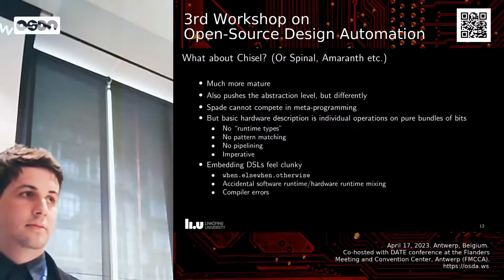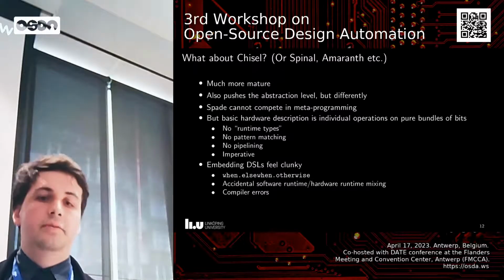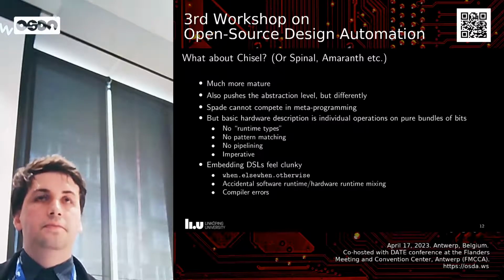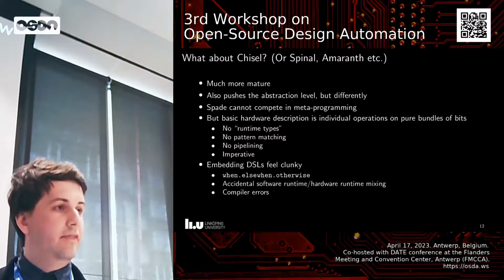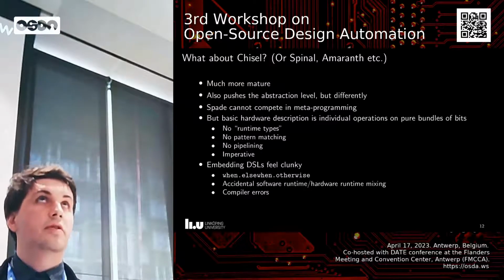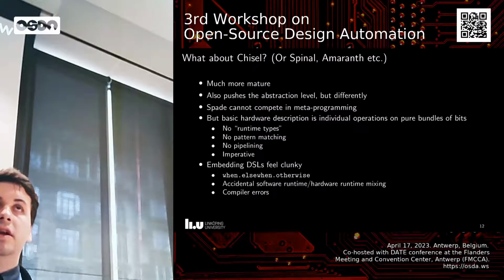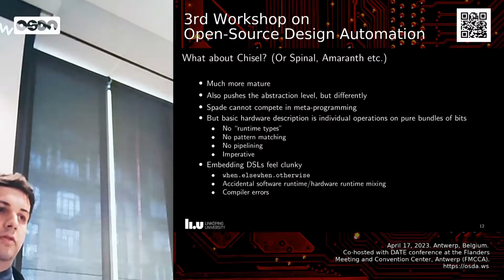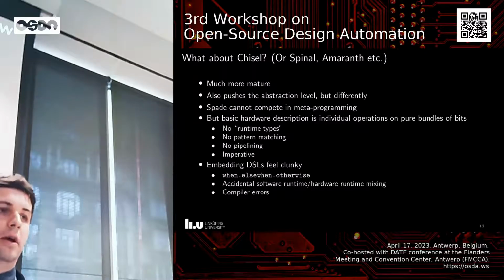Could you give us an example of what you or others have designed with this? Sure, yeah. So it's kind of early stages still. I have a working RISC-V processor, a 5-stage pipeline thing that only supports the base instruction set for now. I've built the controller for a research project I'm working on, which is sort of doing dynamic programming. So it's feeding a bunch of stuff into a long pipeline and writing the results back to memories.